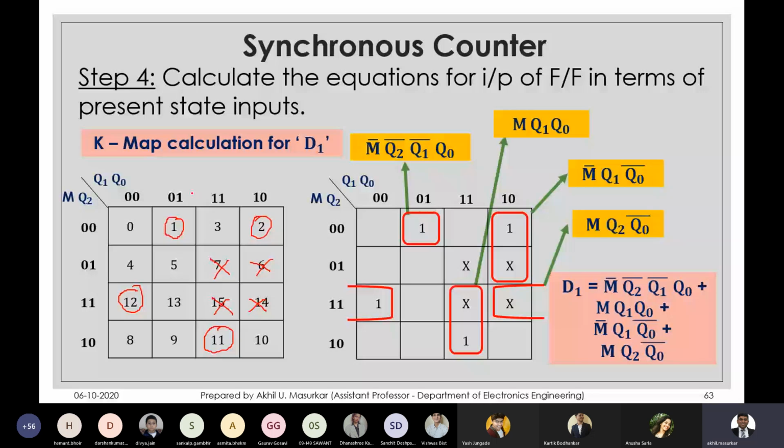So what you will do is take two input AND gates and connect them to another 2 input AND gate. So this is a 4 input AND. This is what you will do in DSCH. Here you can directly use a 3 input AND, but here we don't have a 4 input AND. So we can use 2 input AND gates to do this. Come on, design for D0. D0 you will do on your own.